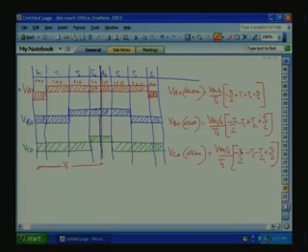So, during the T0 by 2 period, first sampling interval, if you take all the 3 phases, the pole voltages are in the opposite levels. First T0 if it is minus VDC by 2, in the last T0 by 2 it is VDC by 2. So, this we can cancel. So, the volt second, the 0 vectors are not contributing to the average variation. It is only by the T1, T2. So, for VS0 average, VS0 average is equal to VDC by 2 divided by TS into T1 plus T2.